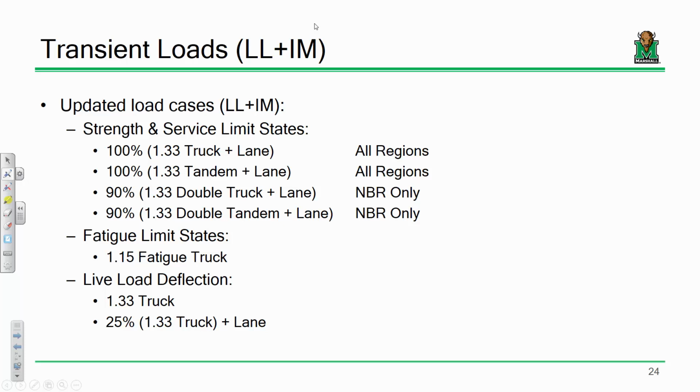Now, if you combine that with your dead load moments and shears, there's your analysis. Now, you've got Mu, compute phi Mn, and if phi Mn is greater than or equal to Mu, it's funny how you just designed a bridge. Does that make sense? Everybody okay with that?